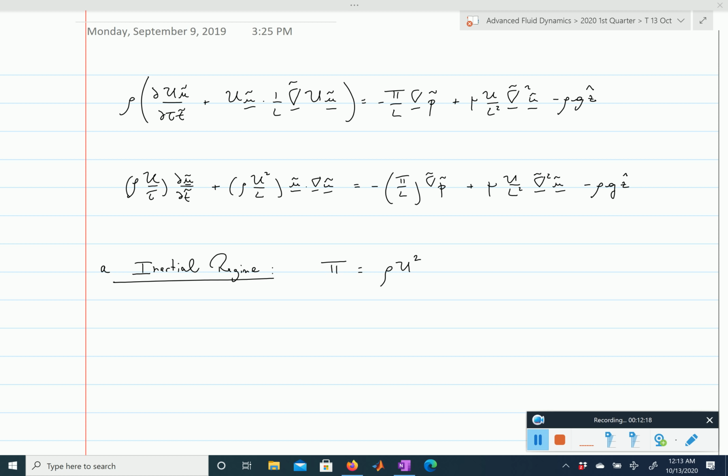And so what we do then is that we take this equation, let's call this equation 1, and we will take equation 1 and divide it by a characteristic scale here for a force per meters cubed, so per volume, and that force will be, you'll see it here, rho u squared divided by L. And so we divide every single term by rho u squared divided by L. Note that in front of this term you will have nothing left.